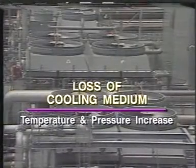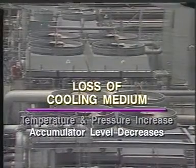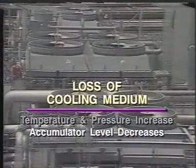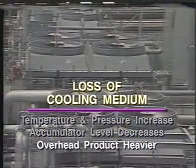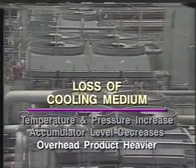When there is not enough cooling water or air going to the condenser, tower top temperature and pressure will suddenly increase. The loss of the cooling medium will cause the liquid level in the accumulator to decrease because hot vapors can no longer be condensed to liquid. A higher temperature also means that heavier material is driven up the tower, so the overhead product becomes heavier.